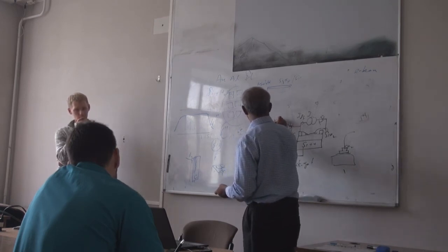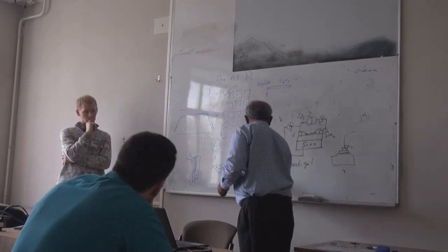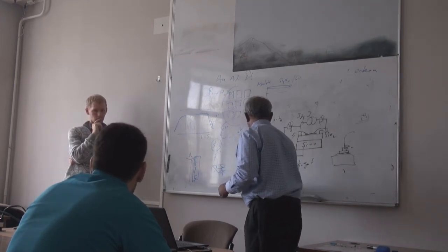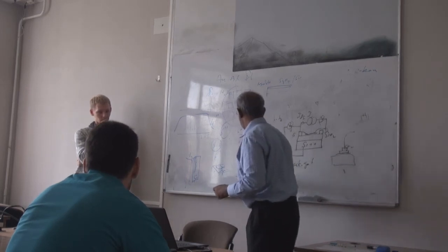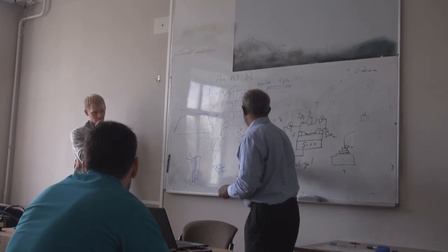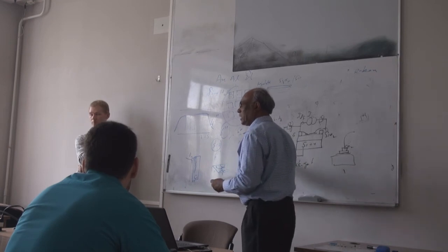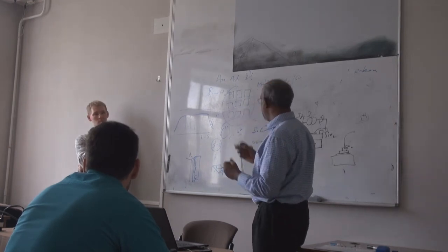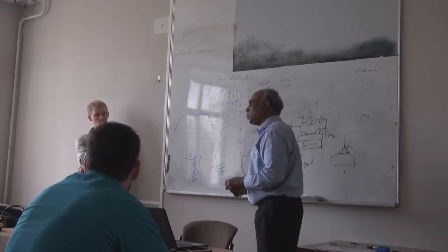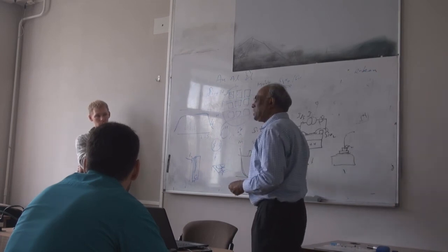Typically these are P-type material, so they show this kind of behavior, because it's on for negative voltage and off for positive voltage. If it is metallic, it is constant. There's no gate dependence. If the contacts are close enough, they can show ballistic transport. So you can easily tell whether it's semiconducting or metallic by this gate voltage dependence.